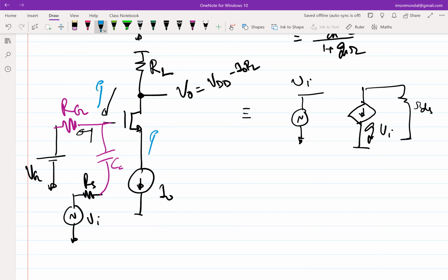So once you know the problem, the solution is easy, right? So you should not allow the source to move at signal frequencies, because you'd want this configuration for DC biasing. You want both to move in the same direction for DC, but you don't want the source to move for signal frequencies. Then what is the solution? It's almost equivalent to saying that this has to be constant bias, right? It's almost as if the source is biased with a constant voltage, right?